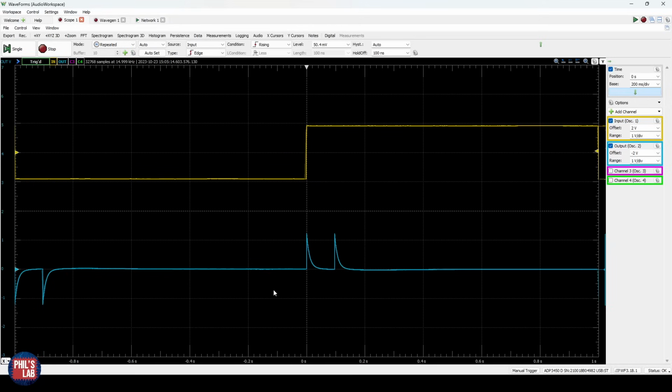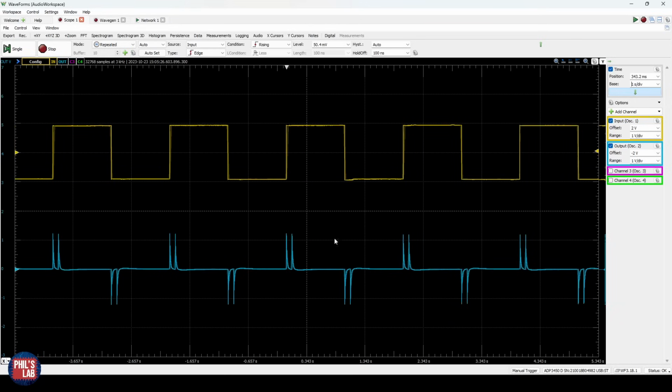and this is exactly what we expect from our comb filter, and of course you can see the same thing on every other transition. Remember, this is with the high-pass filter in place due to the hardware. But this quite nicely illustrates the original sample plus the copy sometime later, in our case 100 milliseconds later.